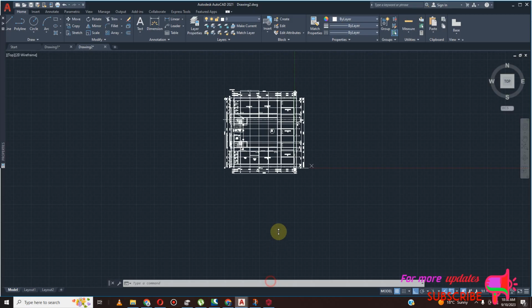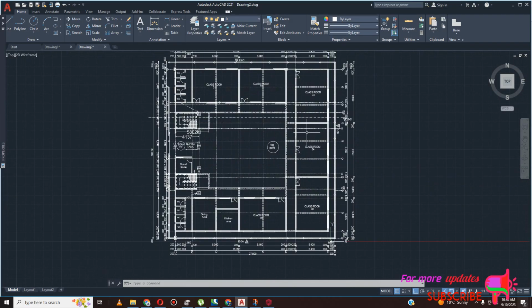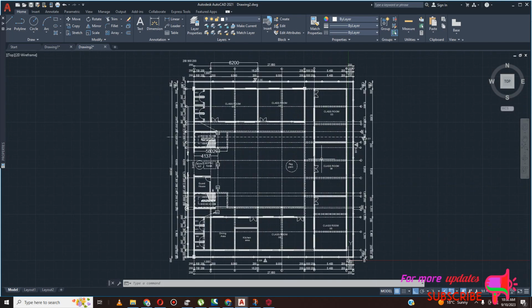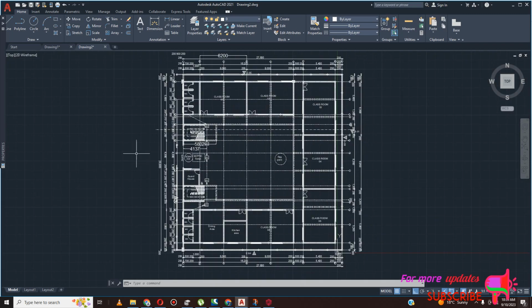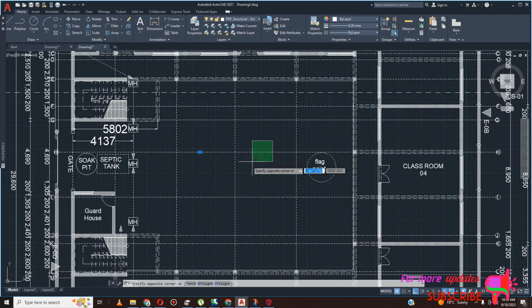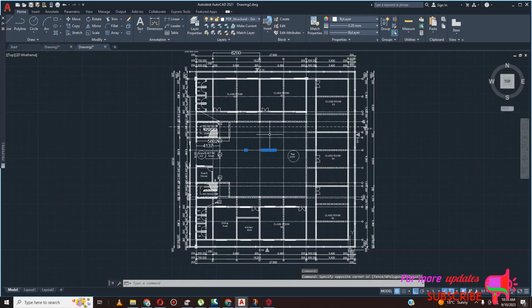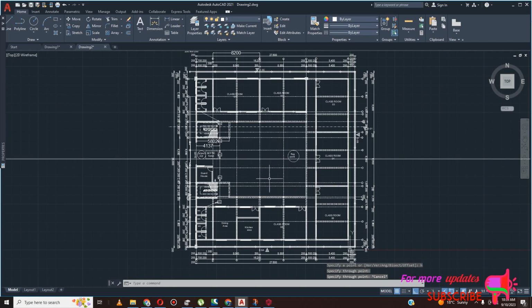So the other most important thing is we don't need to model the entire structure. If you know symmetry, you can tell that there is symmetry in this structure because there is a center line around this point, around that grid. So you can see this. There is a center line around somewhere from, I think, here. Let me check XL H. There's a center line around there.